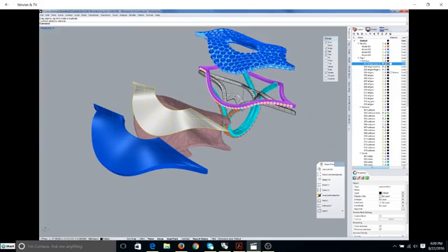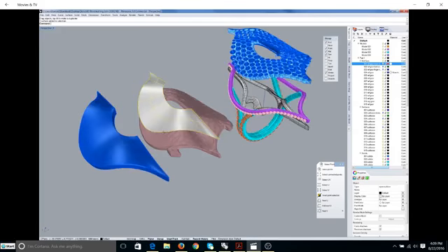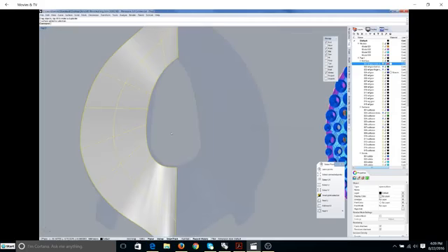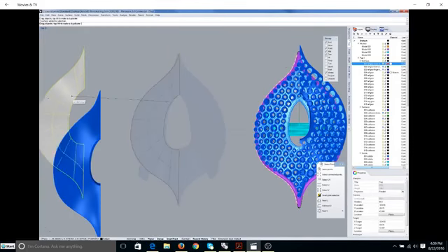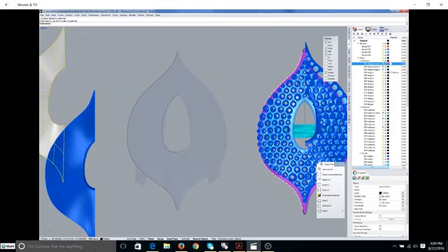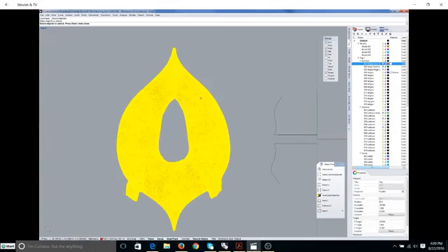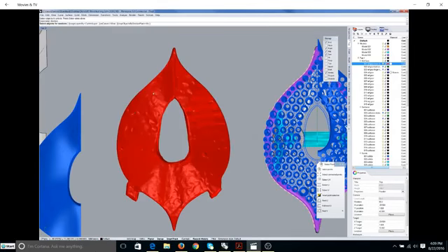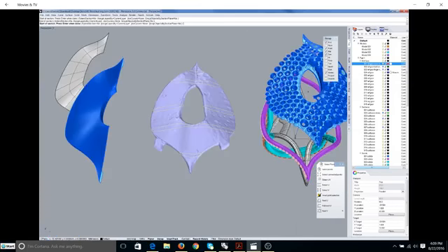So that's one way of capturing it in Rhino. Alternatively, you can also use the section tool in Rhino to capture information. So I'm going to unlock this. And if we go to the section tool in Rhino, we'll highlight this, and I can go in now, and just by coming across here, I can start extracting cross sections off my part. How you want to get your information is really up to you, but this is another alternative way of creating some information.